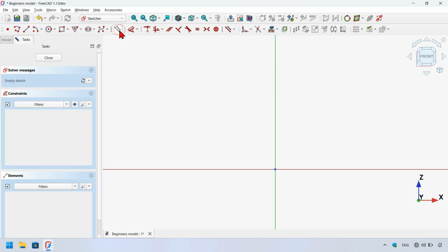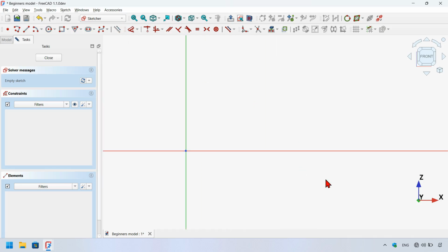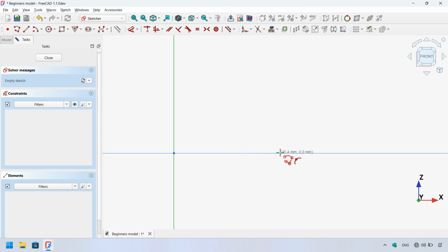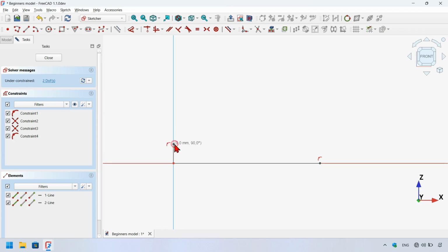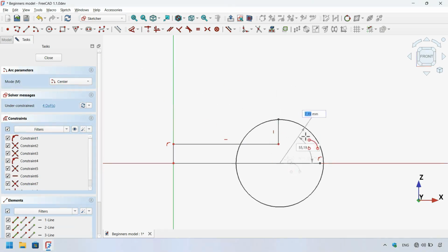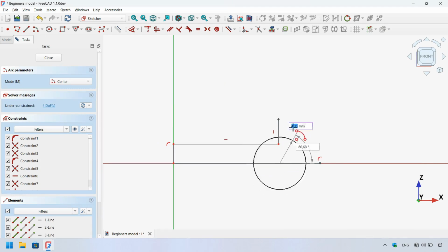And now I change to normal geometries here and I zoom in. Next I select the polyline tool, and first here I will create this horizontal line, and now this vertical line, and next this horizontal line and a vertical line. Now next I select arc tool, I click on this line, and now I create this arc on these 2 points, and I have this.